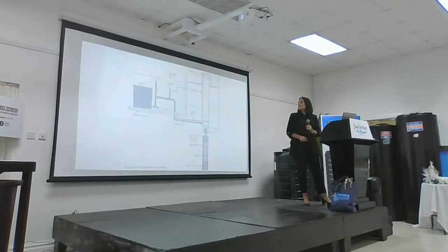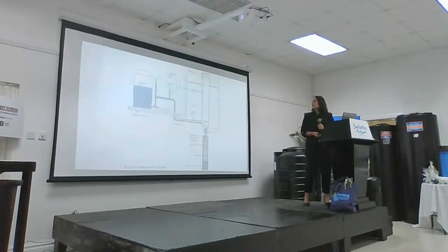There are many additional parts that make up your water system. Some of them you can see here, including the well cap, electrical control box, pressure switch, and a faucet on your pressure tank. We can't stress enough the importance of a properly sealed well cap. So many systems we come across have missing bolts or are cracked. Your well may be where your water comes from, but